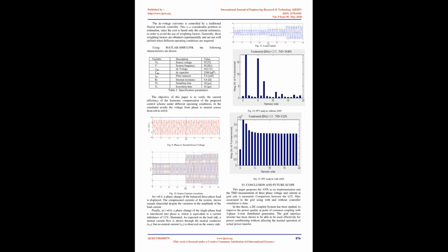The amplitude of the converter reference current must be changed by addition of an active power reference signal, with the D component, to keep the DC voltage constant. By applying inverse Park and Clarke transformation, the resulting signals are transformed back to a three-phase system. Below, Fig. 7, main Simulink circuit for the nonlinear loads with shunt-connected APF.